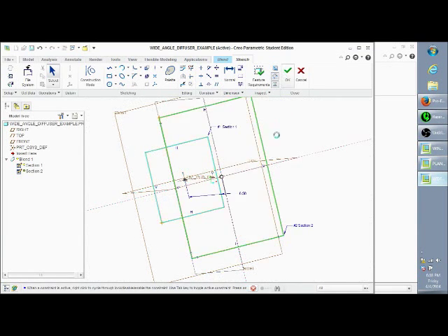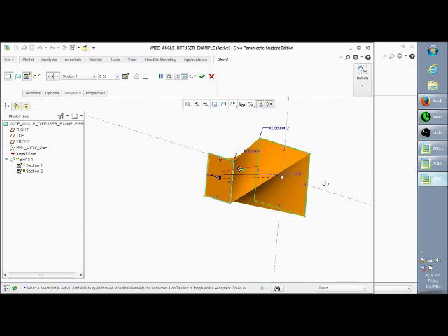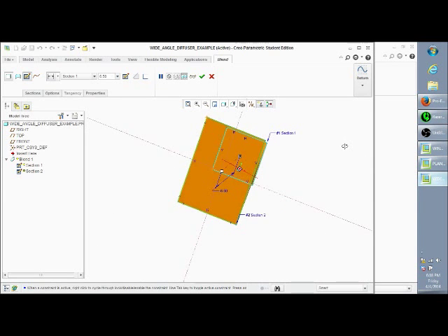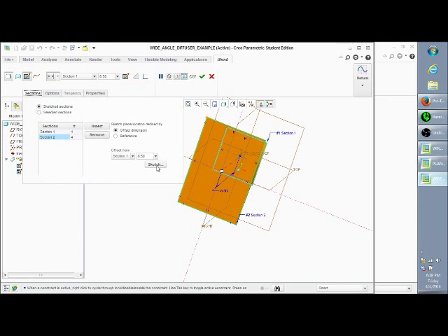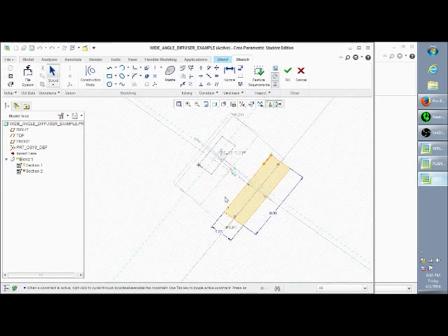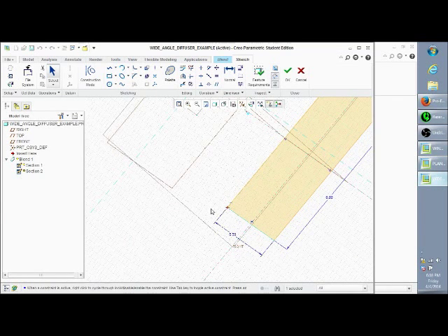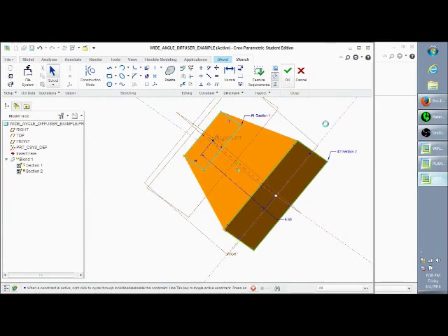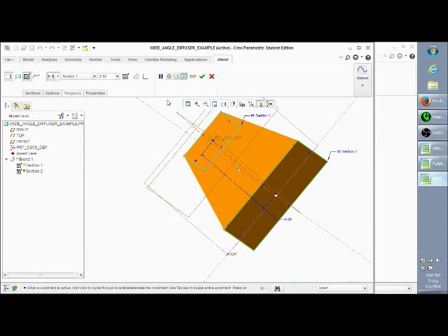So I'm just going to select OK, and that's what can happen to your protrusion if you start from the wrong starting point. So I'm going to go back in and fix it. You can probably hit Control Z. That might fix it too. Pro E is not really consistent with Control Z. If you have already clicked outside, like over here to the side, it will not go back. It's kind of funny that way. Okay, so we've actually got the shape that we want now. So we just go ahead and select OK.